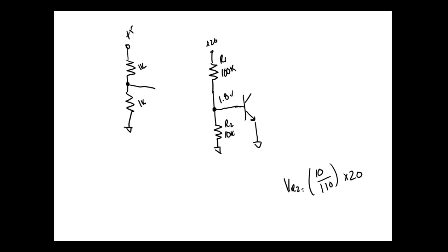Got to drop 5 volts. Resistors in the series circuit, the same size resistors in the series circuit drop the same voltage. I got to drop 5 volts. So how much does each one of those resistors drop? Shouldn't have to use your calculator on this guy. 2 resistors the same size, they're going to drop the same voltage in a series circuit. That means I should measure about 2.5 volts up there. That's something y'all should know, guys. So 2.5, they're the same size. 2.5 plus 2.5 is 5 volts, right?